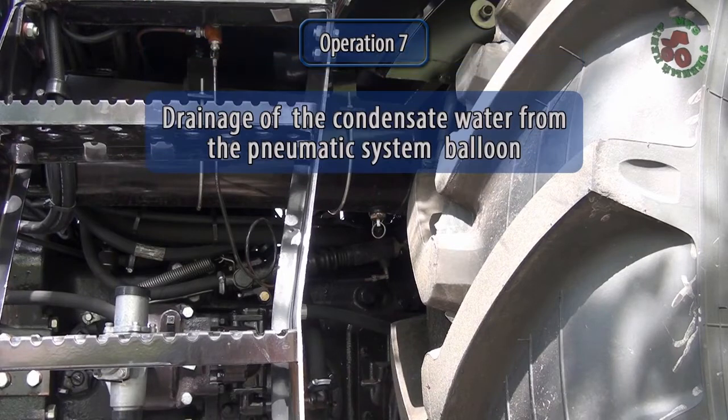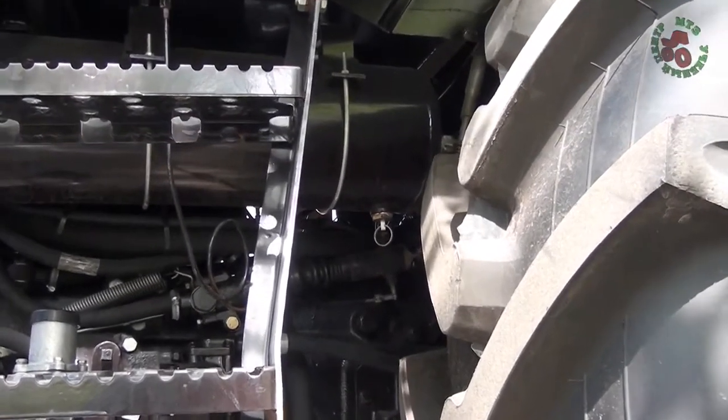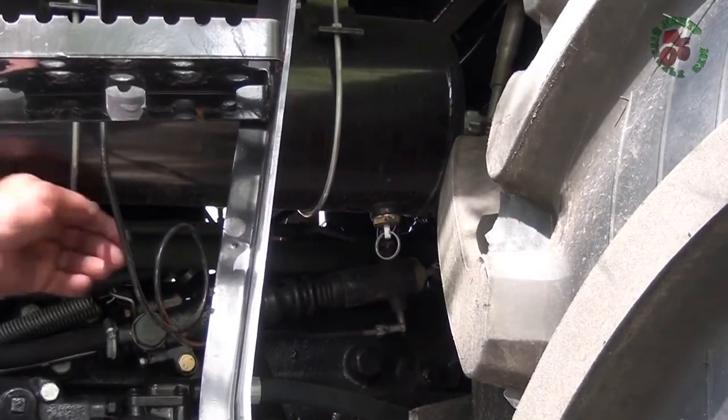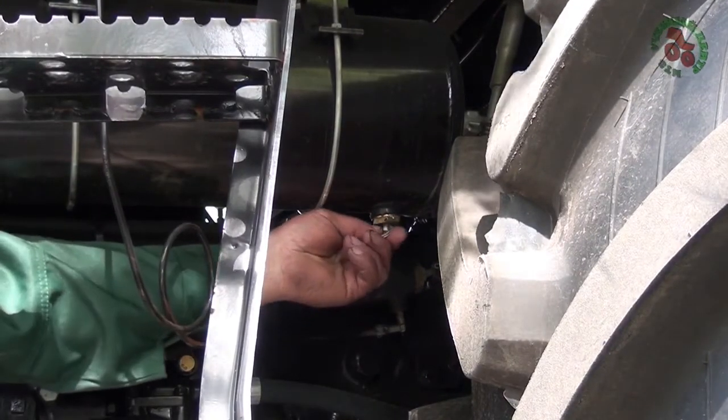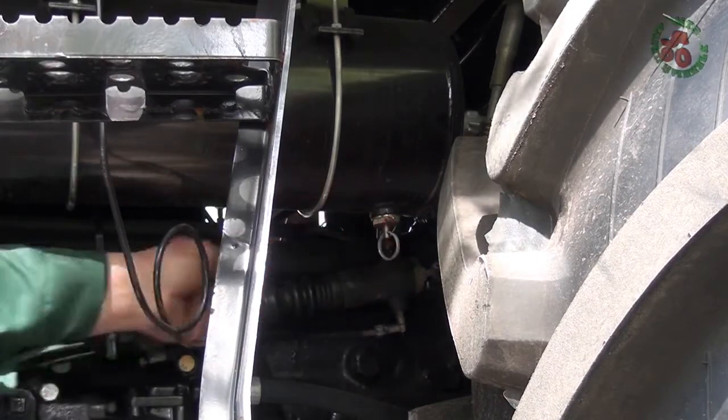Operation 7. Drainage of the condensate water from the pneumatic system balloon. For condensate drainage from balloons, pull the drain valve ring toward the horizontal direction of any side and hold it until full drainage of condensate.